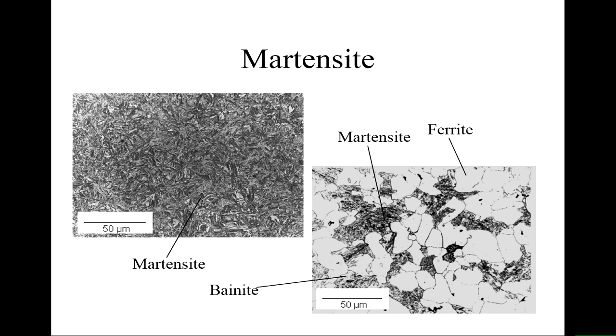And I don't know if you can see, it's got very small spots inside it. It's got very small particles of iron carbide in the ferrite, and that's a bainite structure. Mr. Bain was another metallurgist of repute about 70 years ago, so he had something named after him. And in fact, the strain that causes the transformation from austenite to martensite is sometimes called the Bain strain, after the same person.